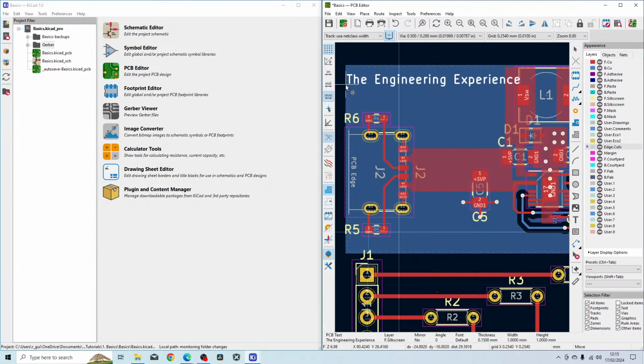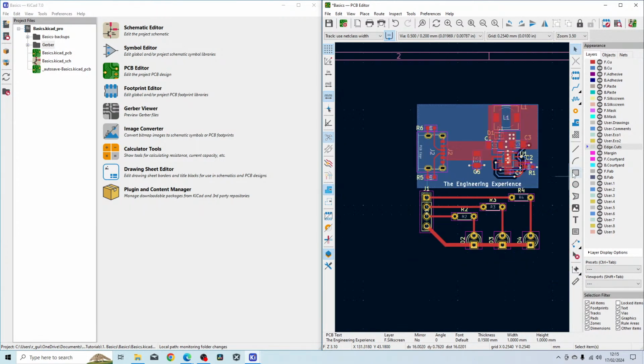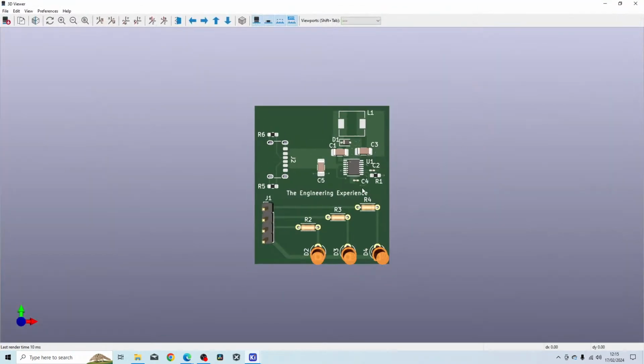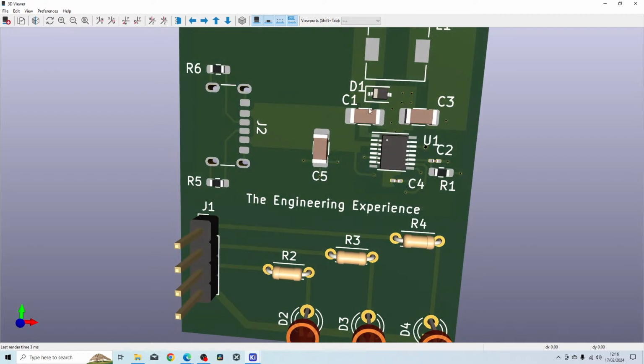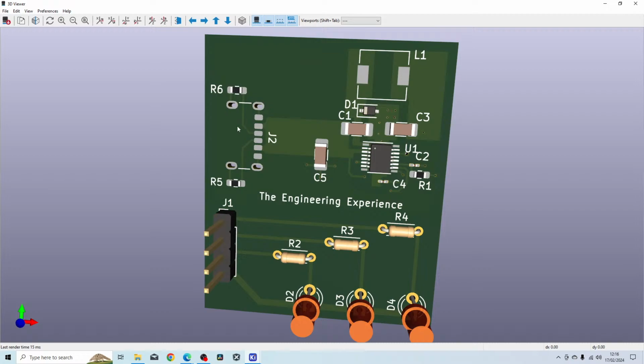That was the earlier design. Well, when I say design, that was the earlier thing that we did. Just a square box around this for now to show you that it's in a decent place, basically, and then we can tinker around with it. So you've got the nice 3V3 buck converter here. All the references and everything, you want to tidy them up. Got the USB-C connector. You want to make sure that the edge of the USB-C connector and the edge of the PCB line up.